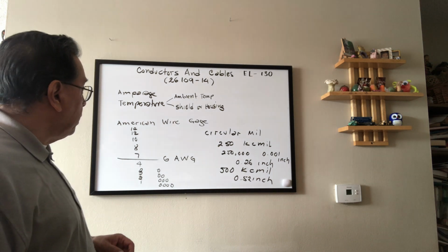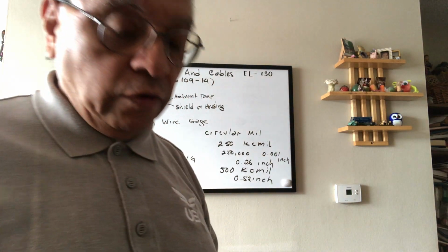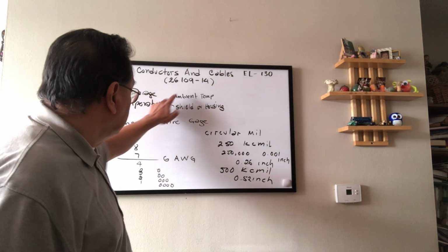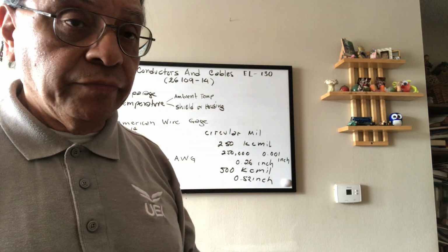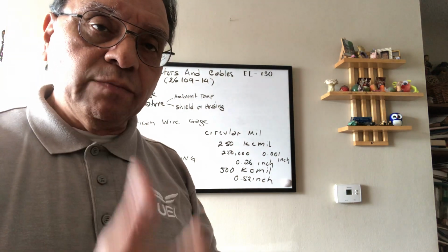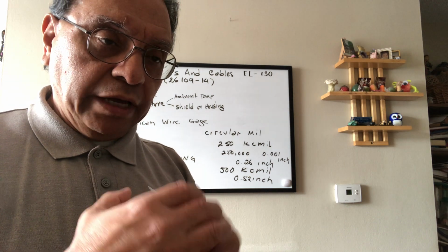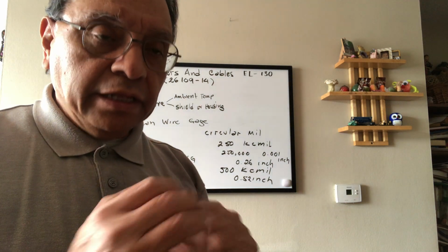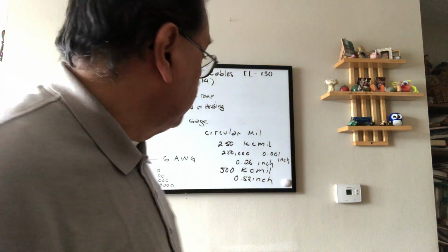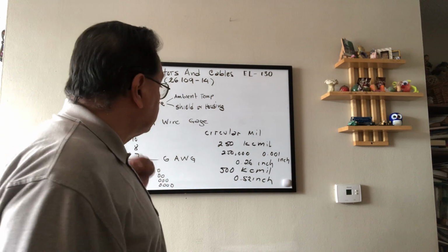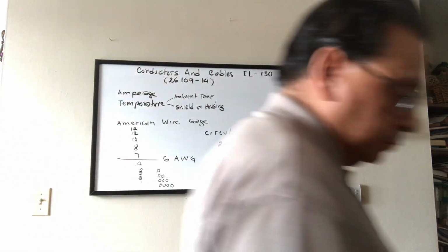Okay. And the other parameter that I need to take into consideration is the temperature. So we combine these 3 parameters. On the temperature, we take into consideration the ambient temperature and the maximum temperature that the housing used to protect, to encapsulate, to house the electrical conductor can support. To select the cable based on the temperature, we use 1 table in the NEC.